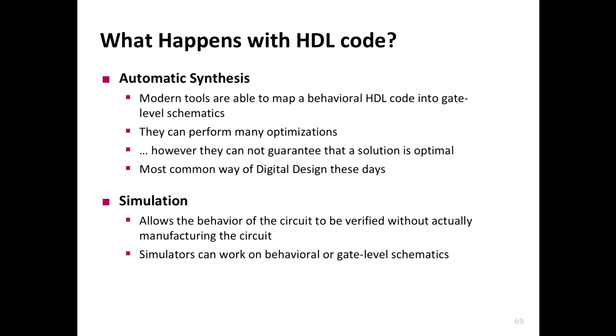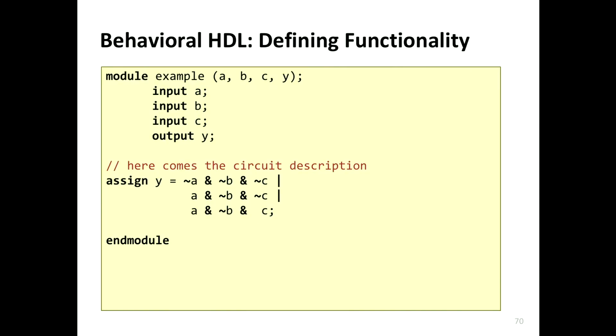Of course, you cannot assume that the circuit the synthesizer generates is going to be the most optimal solution. In general, the majority of times you're going to get a very optimized circuitry. But if you are looking for some very advanced manipulations, like you want to optimize for power or reduce gate count, you have to be very careful how you write the Verilog. But these are advanced, so you don't have to worry about it right now.